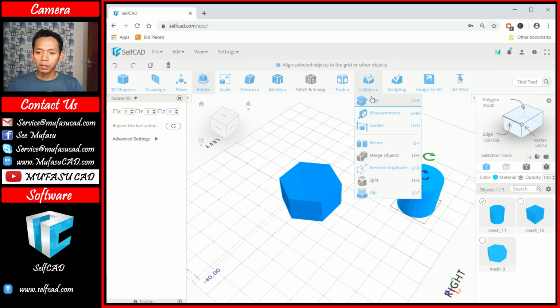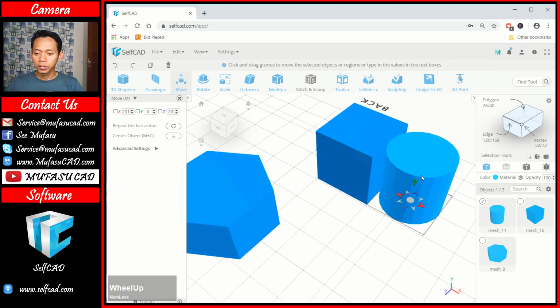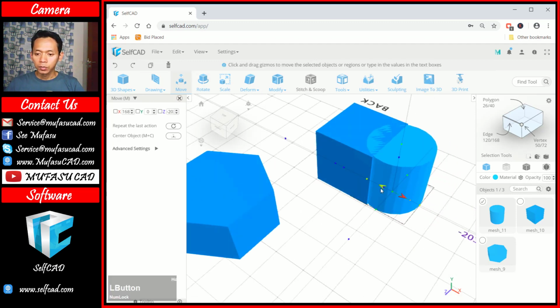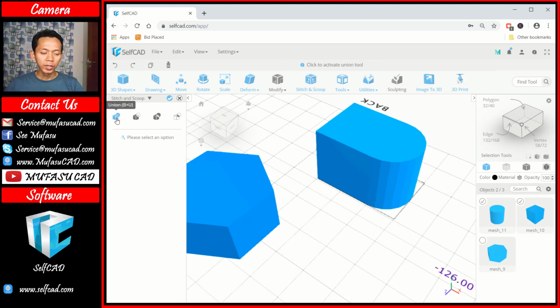You can click Utilities, Align, and I will change the reference to mesh. Okay, and then I will use a move command to move this cylinder object to this point. Okay, next we can select these two objects and combine them with the union command. You can click here, Union, and click OK to combine.